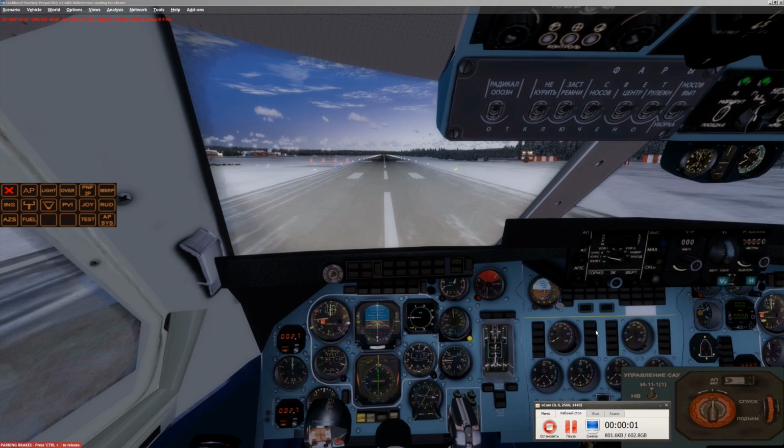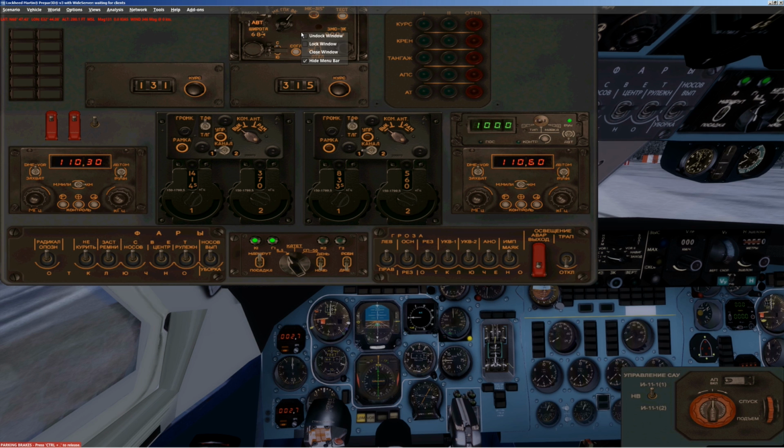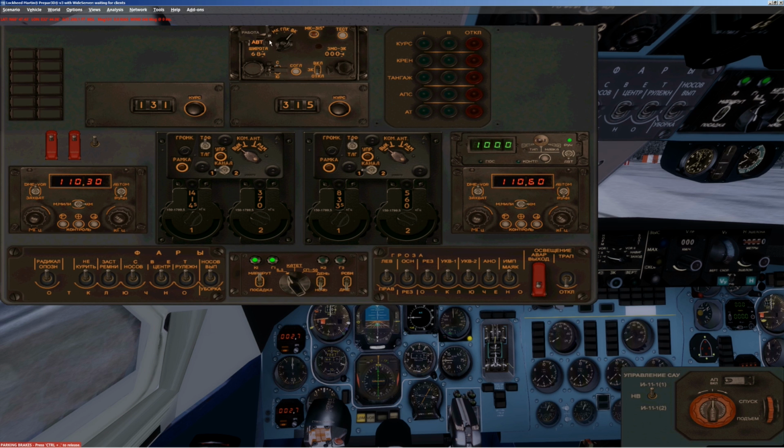On the runway, I forgot about coordination with the navigation system, the primary navigation system. Go to overhead, switch the selector to MK, magnetic course, set up the latitude, current latitude 68, and press the alignment button.